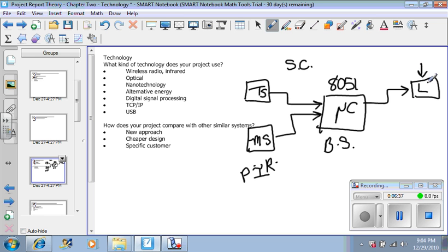And I can give it using a BJT transistor or a MOSFET transistor or a relay coil or many other different ways. But in my design, I'm using a MOSFET to reduce the amount of current needed from the microcontroller. And I'm not really thinking about speed, so I've decided on a MOSFET.